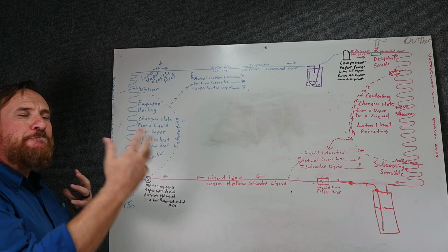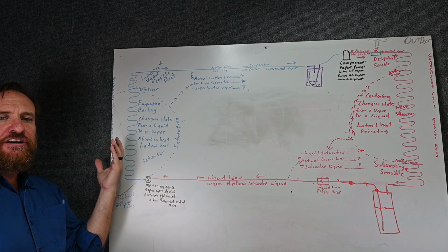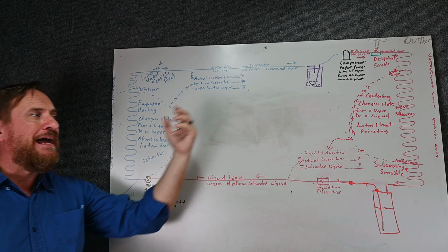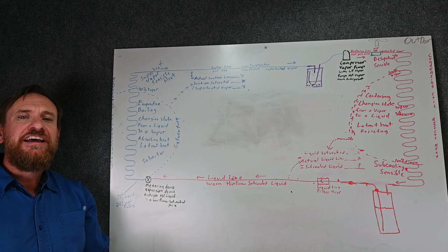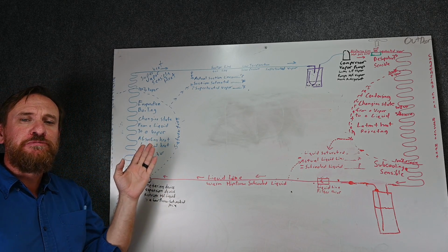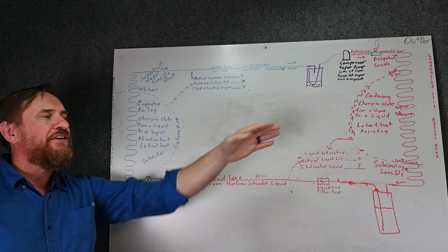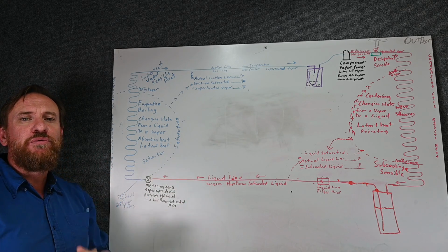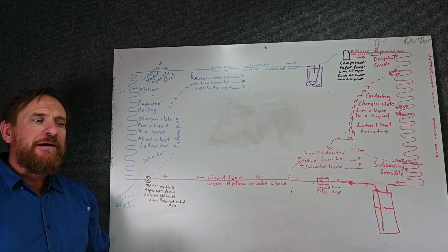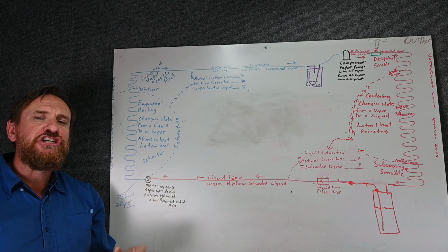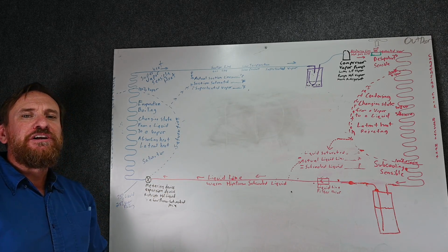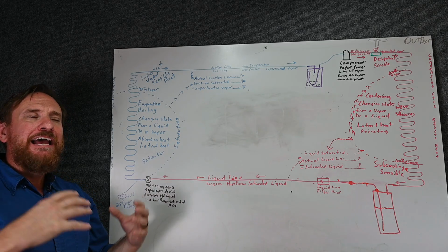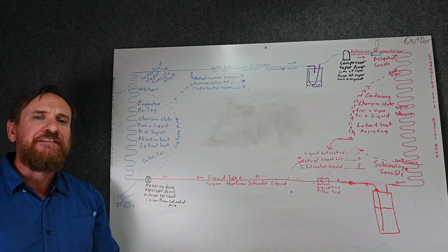MeasureQuick takes into account many different variables such as return air wet bulb, supply air wet bulb, outdoor air temperature, line temperatures, and it does a whole lot of calculations to find out what your suction pressure should be within a range and what your head pressure should be, still within a range. We're going to talk later on about many of the little different numbers individually that the app uses to find this one number. And then eventually we're going to introduce you to the MeasureQuick app, and by that time you'll have a full appreciation for everything it does.